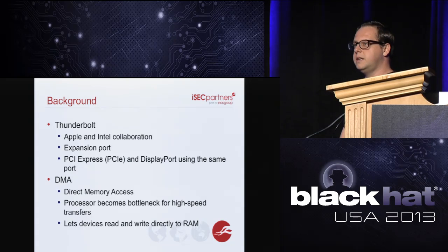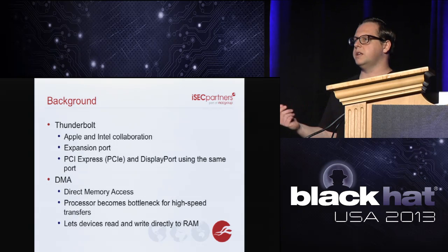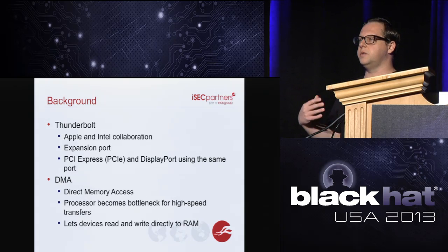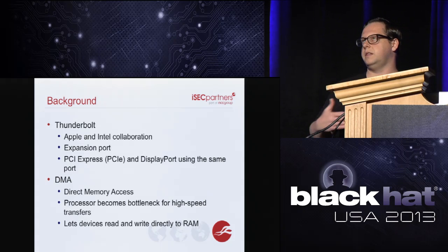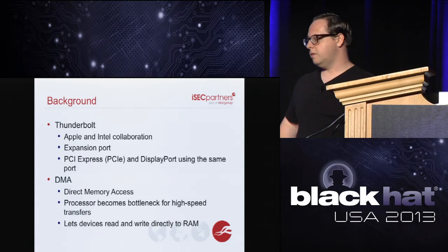It stands for Direct Memory Access. Back in the day, when a device needed to access memory, it did something called programmed I/O. A device would contact the processor. The processor would take the address that it wanted, store it in a register, then go fetch that memory and come back. So the processor was the middleman. And as the processor became faster, devices still stayed slow. So the processor would have to wait around for the request to be finished by the device. It was a horrible performance hit. So what the engineers decided to do was, well, let's just have the device contact the memory directly and allow the processor to continue on doing what it needs to do. So that was the solution.